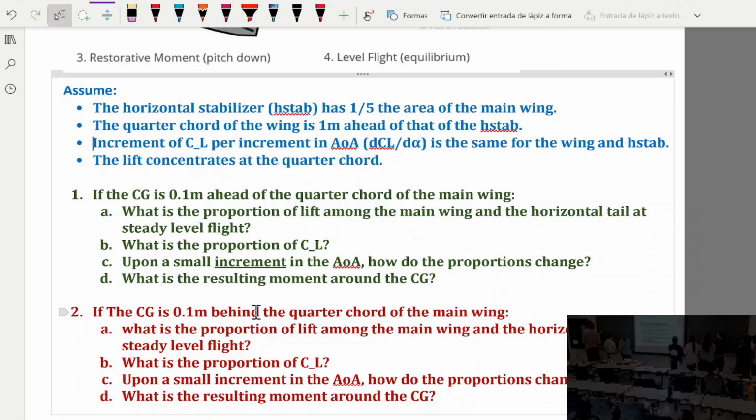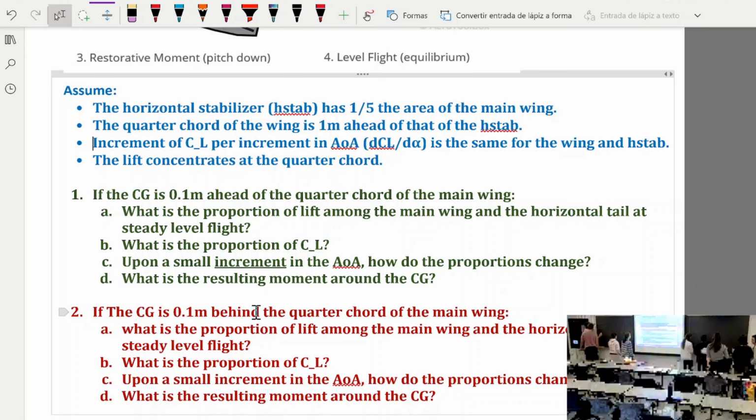Because the acceleration of the plane is 0. And that's okay. As long as your center of gravity is ahead of the main wing, the tail has to provide a downforce. That makes sense. Okay. And you're going to have a reaction moment. I think the states are always going to maintain the same proportion to each other. So this is already enough, right?